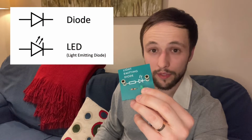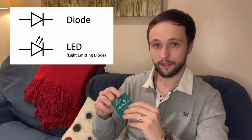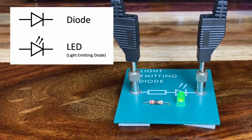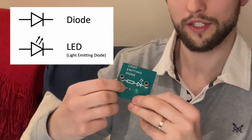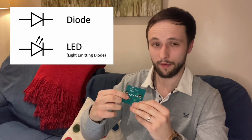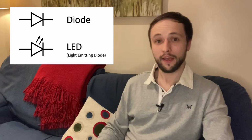This is a diode. This only allows current to flow in one particular direction, unless you overload it and break it. This particular diode is a light-emitting diode, or LED, and just like any other diode, it doesn't have any resistance, which is why here it's connected in series to a resistor. This is to try to minimise the chances of me blowing it up by accidentally putting too much current through it. And lastly, I've got a couple of examples of switches.